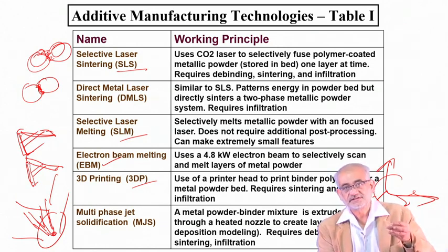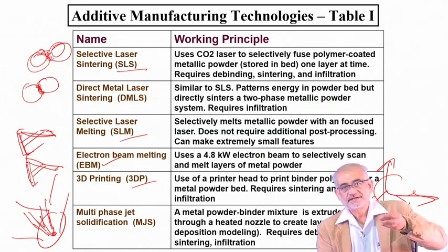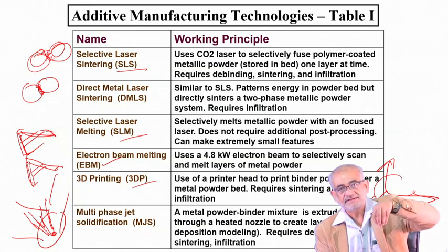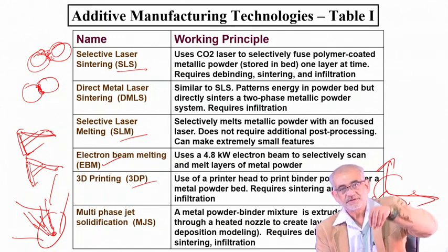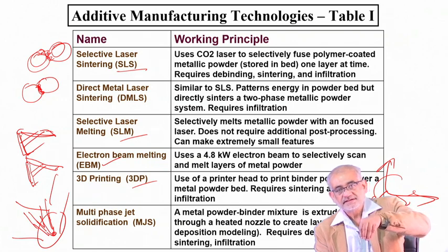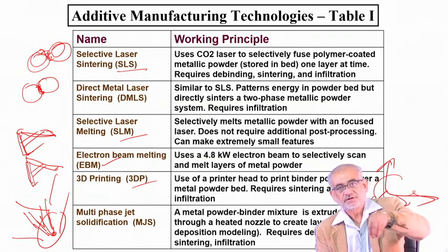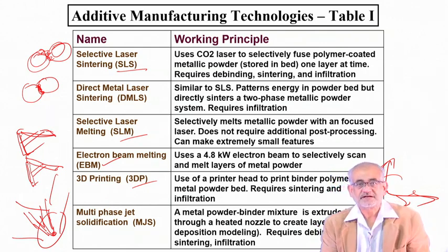The arm can rotate, move, and translate to create. Essentially this robot arm will carry the laser beam, the powder feeding system, and the concentric nozzle, and both will act simultaneously. If it goes through a circular, vertical, or lateral motion in X and Y direction, it can create practically any shape.